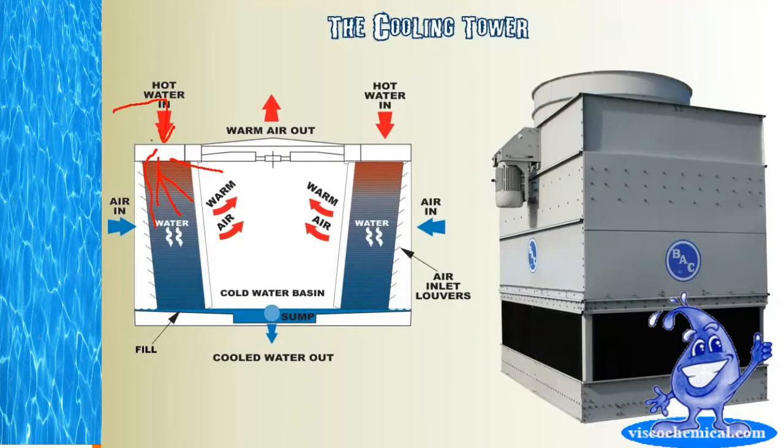This diagram here kind of represents one where it would just hit this top here and it would just kind of rain down across here. Raining down by itself would actually help cool the water down just with the air naturally coming, with the water pouring out and going across these little fins that are here. That'll actually give it a little bit of cooling. So sometimes you'll use that as a first stage of cooling.